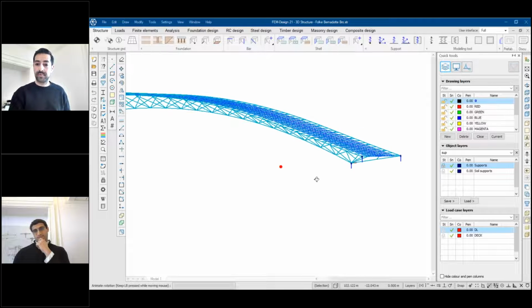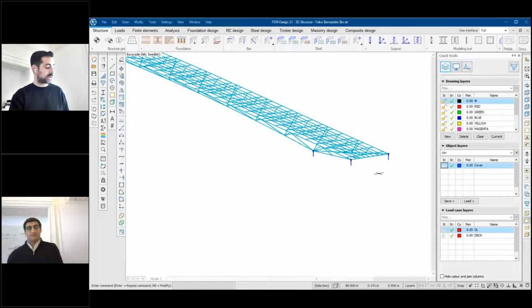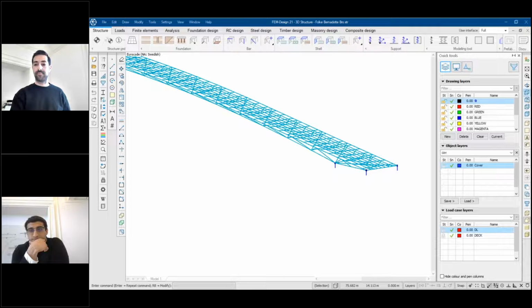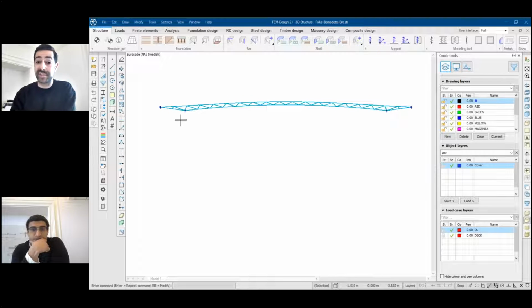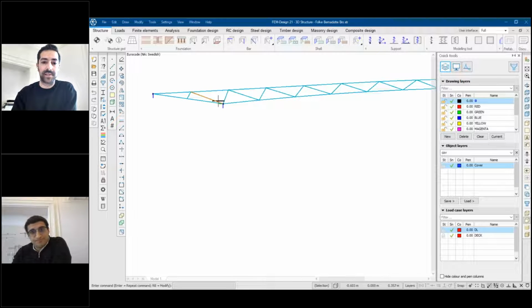And it is a very special support configuration because it has a triangle at the ends, which also changes in height. And it's a continuous system. So you could say it's a 3-span bridge, which will give this a very special behavior, more or less like a clamp system. Basically, this support will take compression loads and these supports will take tension loads.